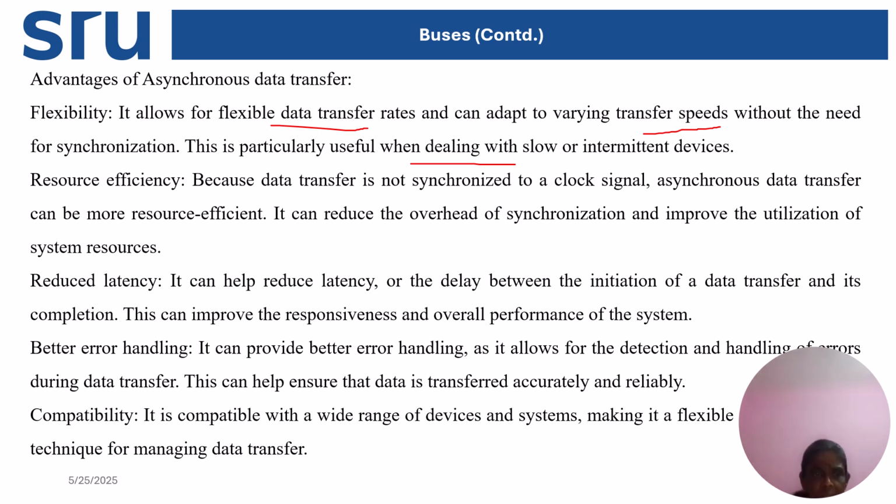And then the next feature, resource efficiency. Because data transfer is not synchronized to a clock signal, asynchronous data transfer can be more resource efficient. So available resources will not get wasted. It can reduce the overhead of synchronization. Overhead of synchronization means that for giving synchronization we need to add additional bits, sync pulses.